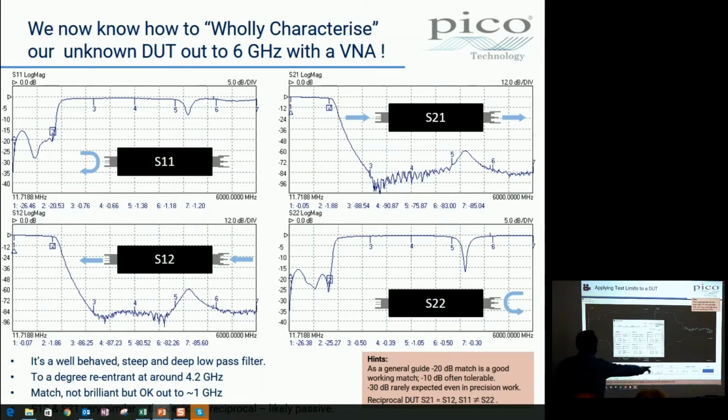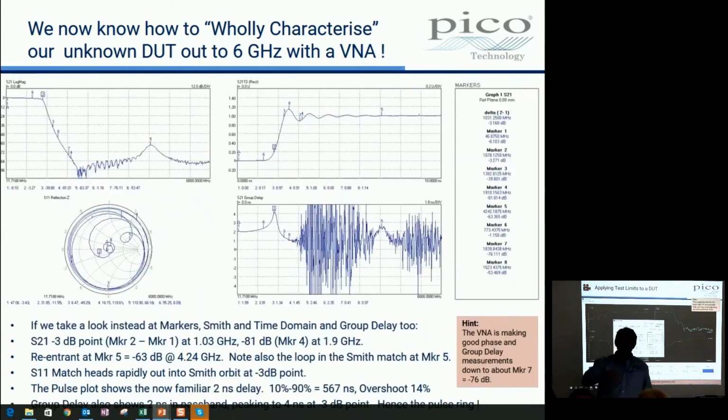All right, so when I use the limits button in the bottom right hand corner, I get limits for each of the display channels: 1, 2, 3 and 4. Thank you, Paul. You challenged me earlier for not telling you which was which channel, and quite rightly too. And then each one has a start frequency, a stop frequency, an upper limit and a lower limit. And these are the limits that I've put in there. So you can get those displayed fairly quickly. The limits are different for each plot.